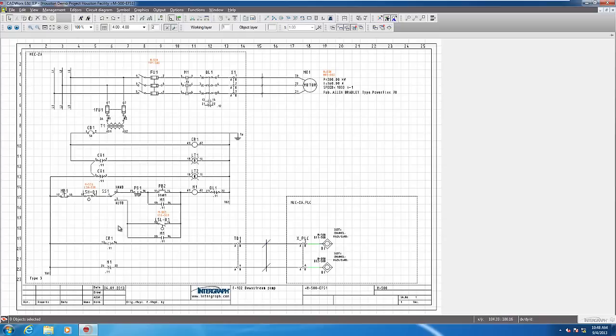So now we already have the primary loop elements assigned to the various items in this template based on the setup. And you can see there, particularly for the motor, that we have data already coming in for it. And so once we've reached this point, now it's just a matter of creating and attaching cables in between the various points. In this case, between the X1 terminal strip and the motor itself.